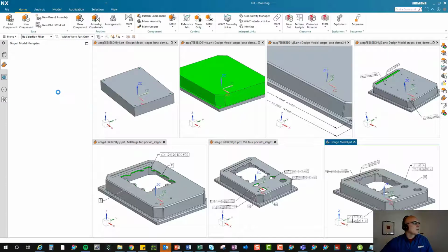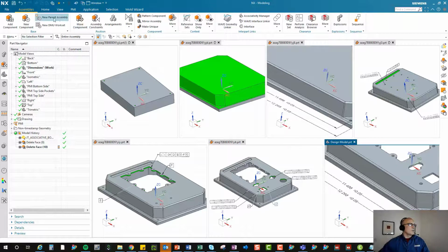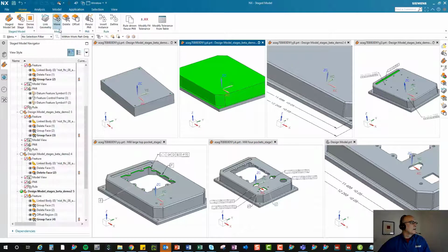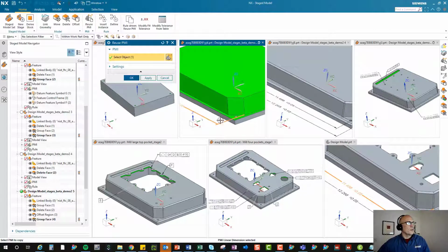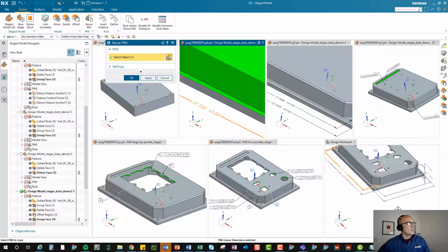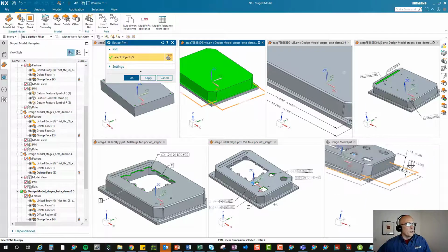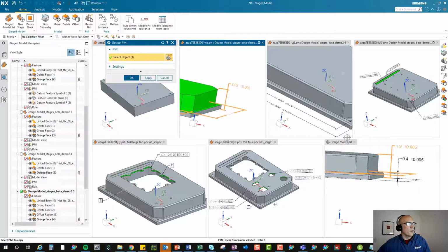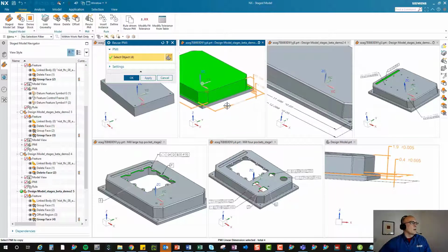All right. So there's my dimensions in my original view. I'm going to pull them out of that. So say this linear dimension here, change a little bit because of my offset. Okay, and then that one there, you can see that that's also changed. And maybe because of the offset I did on the outer surface, that will also update. So it's very dynamic.